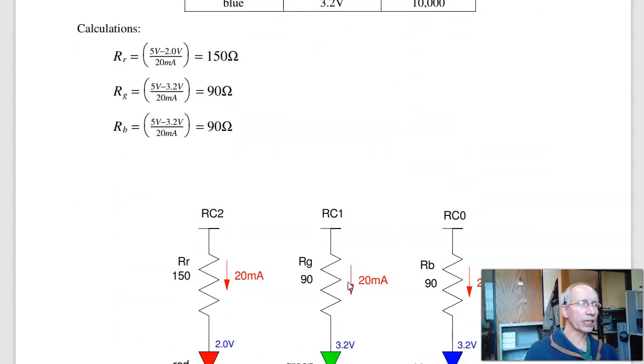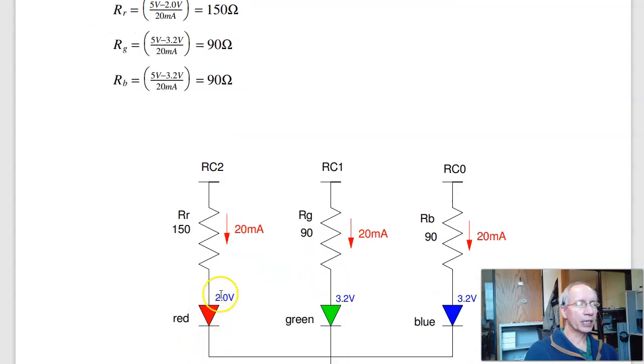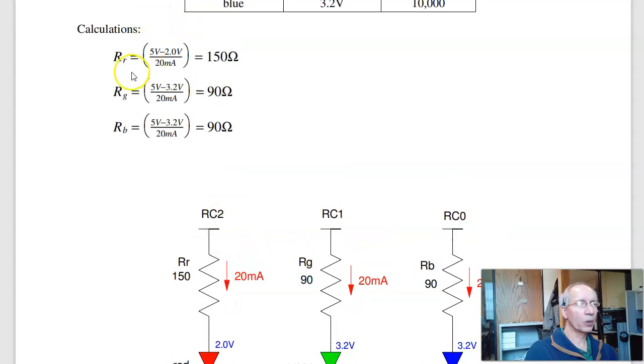Well, LEDs are diodes. The voltage drop across the diode ideally is constant. So at 20 milliamps, this is 2 volts. At any current, it's roughly 2 volts. That's an ideal diode model. The remaining voltage is across the resistor. Assuming the PIC outputs 5 volts, then the current is (5 minus 2) over R. Or going the other way around, the resistance should be the voltage drop across the resistor divided by the current.